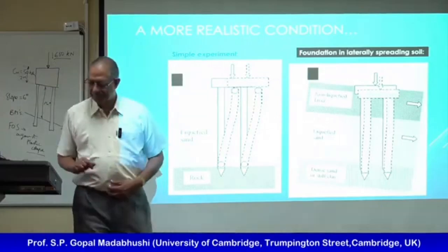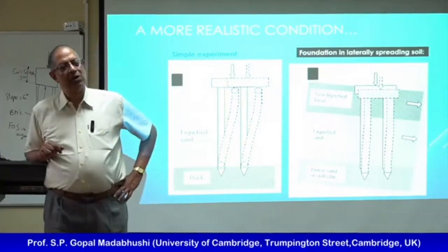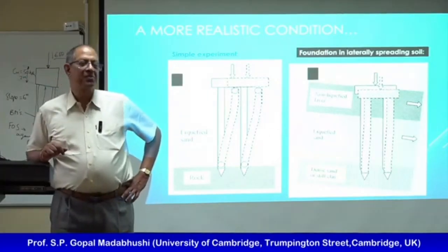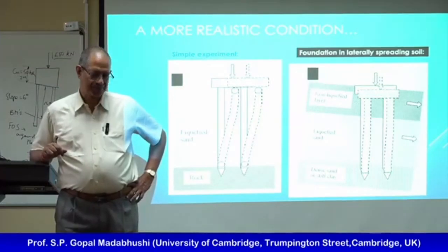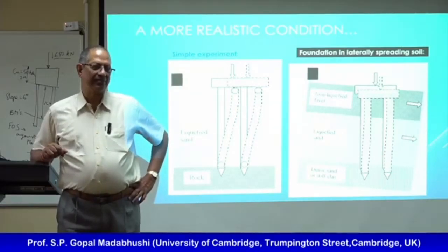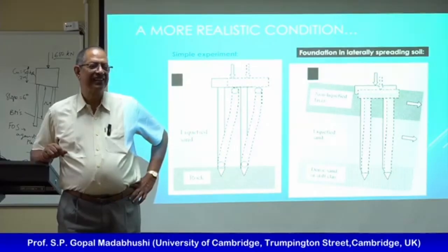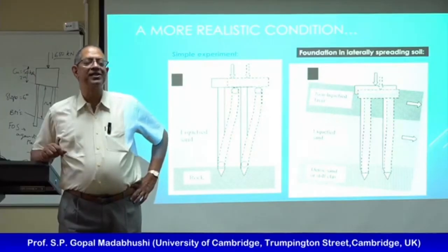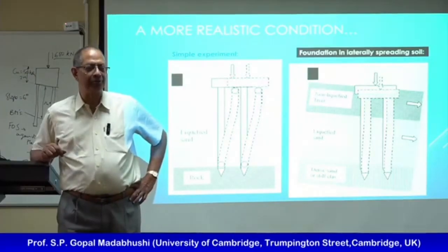Sir, there is one general question. Before liquefaction, suppose we have some properties of soil. We have a particular p-y curve, we have an angle of internal friction. Now, during liquefaction, these properties will change. The p-y curve will be something else. Then psi will almost be negligible. And then after liquefaction, will you get back to original properties? I mean, a long time after liquefaction.